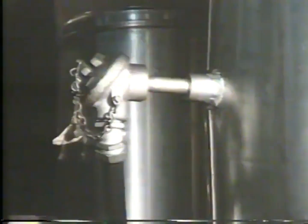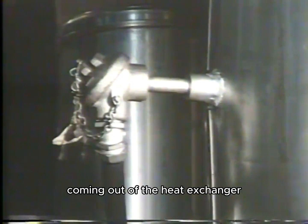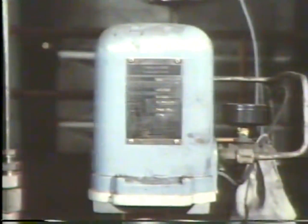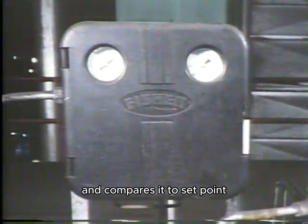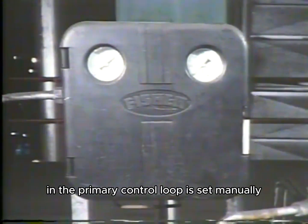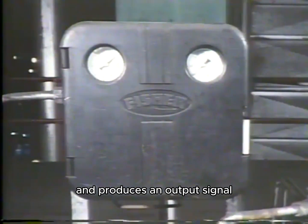The primary element in the primary control loop for this process monitors the temperature of the water coming out of the heat exchanger. This temperature indication is measured by a temperature transmitter like this one. The temperature measurement is converted to a signal that is sent to a controller. The controller measures the signal and compares it to set point. The set point for this controller in the primary control loop is set manually. The controller then computes the difference in the value of the signal from set point and produces an output signal.